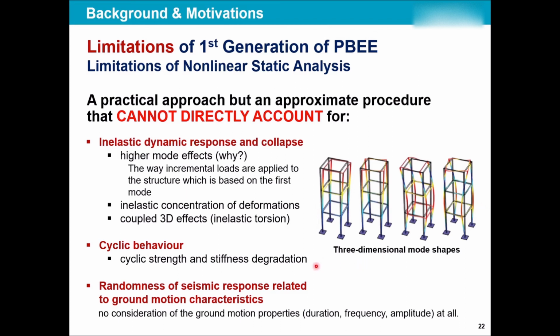And then we discussed before that materials, for example steel, have a cyclic behavior. Because the earthquake is cyclic, the earthquake will push and pull your building. During this push and pull, you will lose strength, you will lose stiffness, and the building will lose its ductility and it will fail. A simple pushover couldn't replicate this.